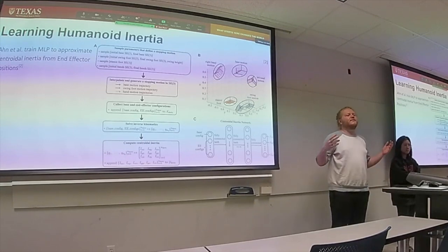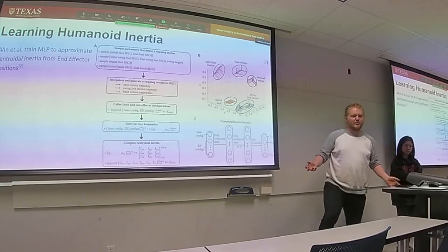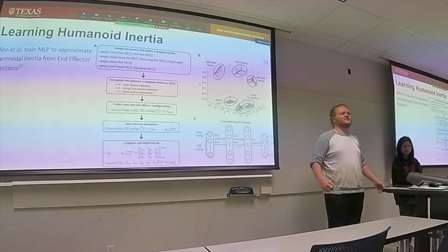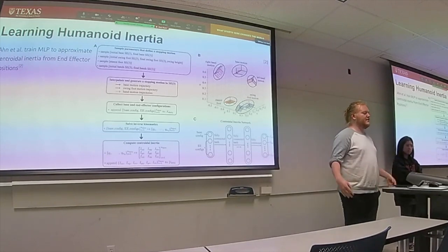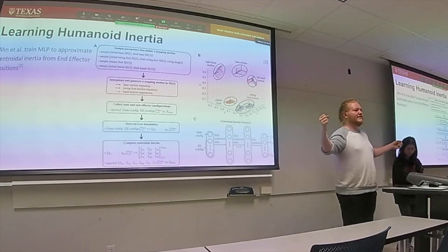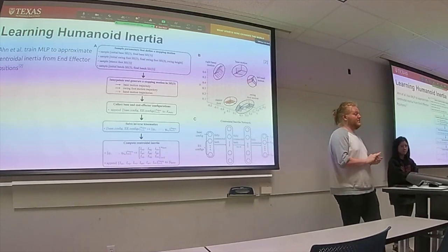For a biped, that doesn't work because stability is a lot more important. You know, you're waving your arms around. I can't just pretend that this and this are the same thing, because they're not. But it's very tricky to take, say, your end effector positions and calculate what your inertia is. That specifically takes a very long time.